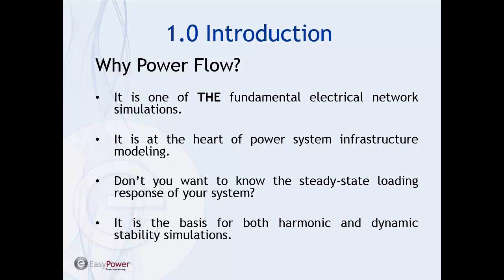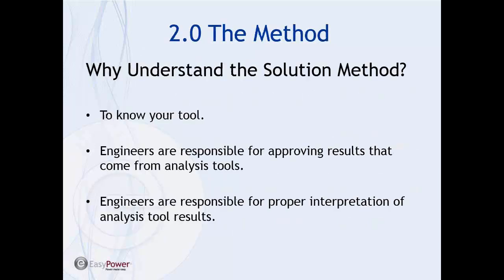Also, it is the basis for both harmonic and dynamic stability simulations. For harmonics, if you want to know your fundamental current that's flowing in the system or your fundamental voltages, you really need to have a Powerflow simulation. And in dynamic stability and transient motor starting, both actually, it is the base case starting point for your simulation.